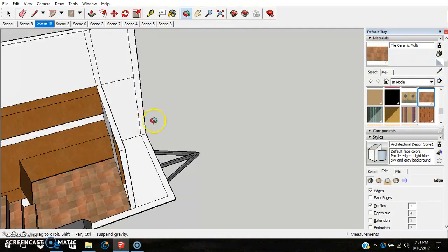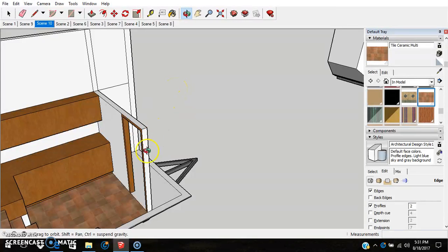I actually was experimenting with some things earlier, and I was thinking I could just kind of maybe bring part of the kitchen in here. So just doing a rectangle, going to come in 6 inches from cabinets, so that would be 30 inches, so comma 30.